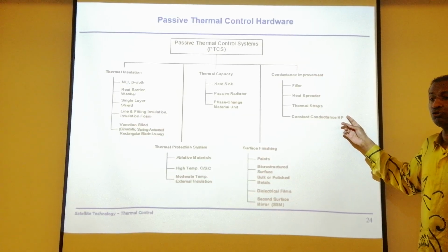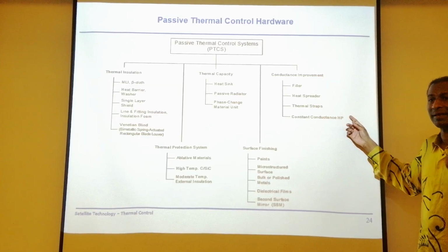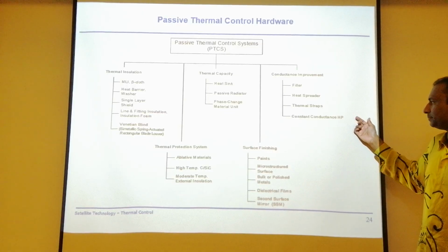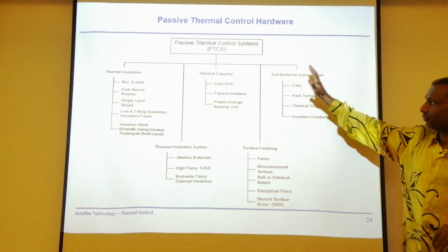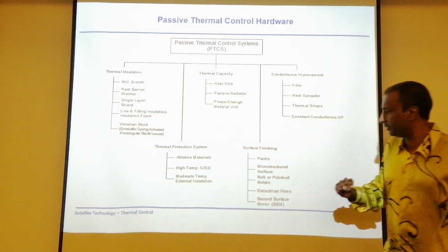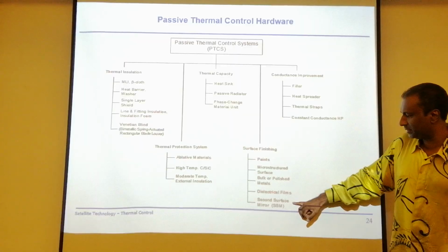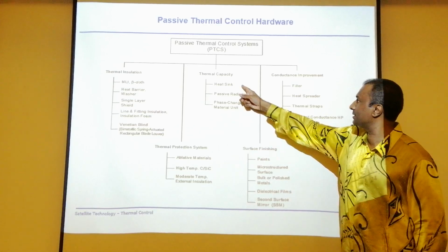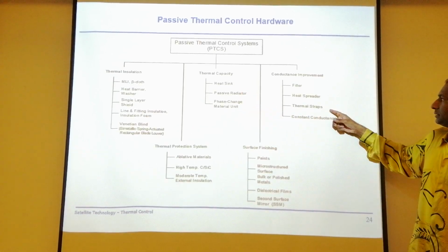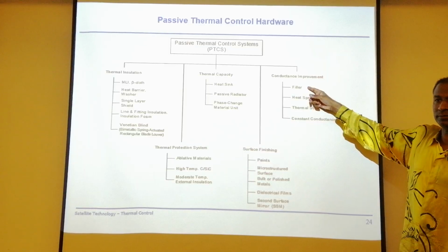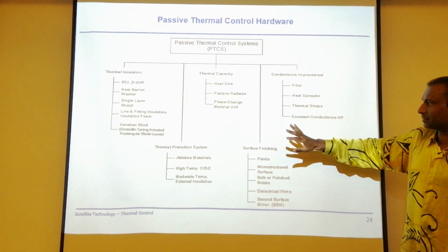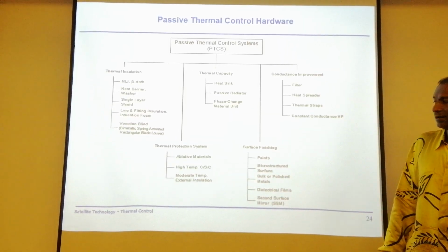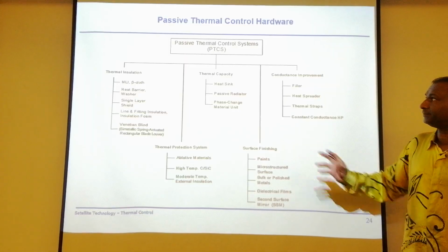As I've said, heat pipes, when you don't put electricity inside, are in passive mode. It happens due to surface tension and the capillary mode. Okay, so you have all these. More important again, paints, secondary surface mirror, multi-layer insulation, heat sinks. You have thermal straps, filler. Yes, you do as well. These are for satellites. The rest, like all this ablation, you may have in capsules, re-entry capsules. Okay, this is the passive one.